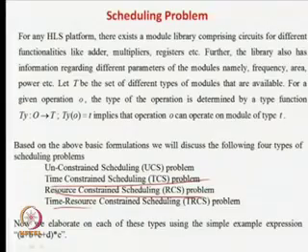So, it may happen that you will take a very long time to do it, because there may be a constraint on the resources, and sometimes the resource constraints may be such that you may not be able to solve your problem. For example, if there is a subtraction operation and you say I do not have a subtractor, then obviously it is an infeasible schedule problem and you cannot schedule the CDFG at all. And finally, we have the time and resource constrained scheduling problem, in which both problems are together, that is you have a definite time constraint as well as a definite resource constraint.